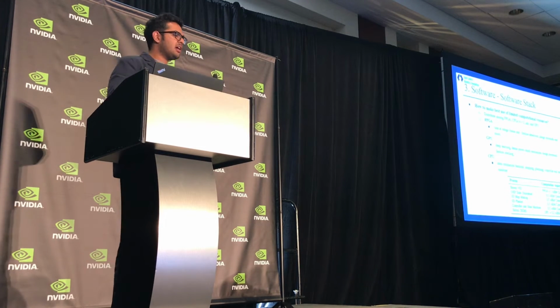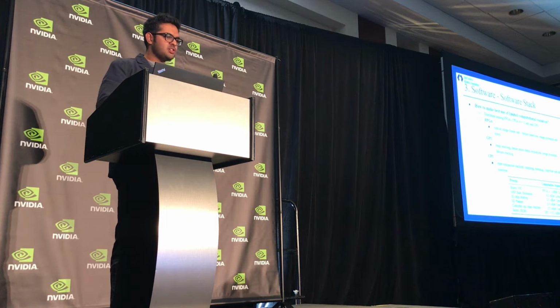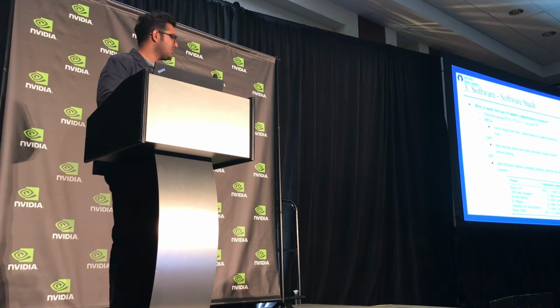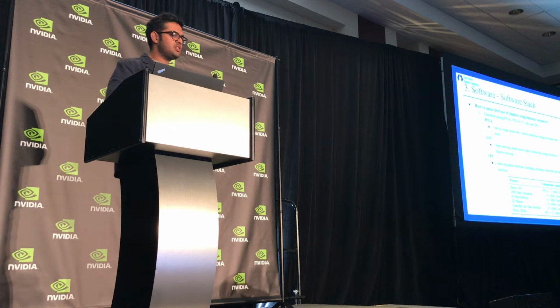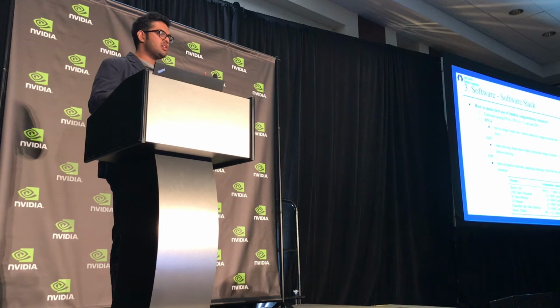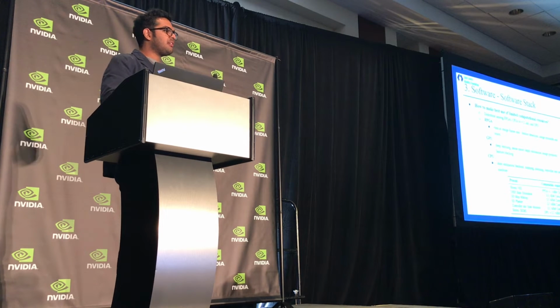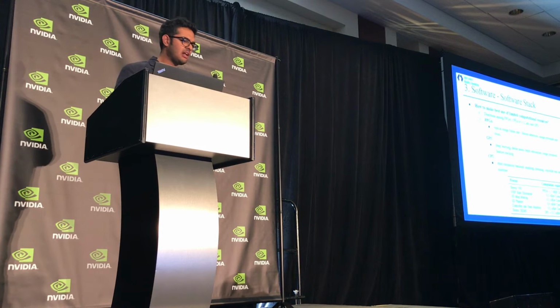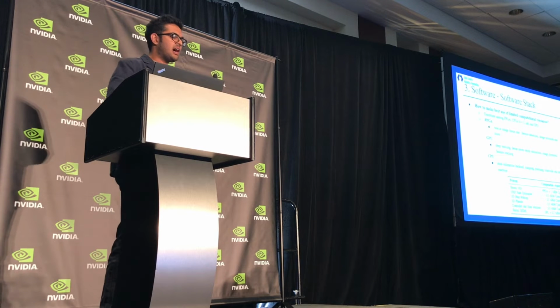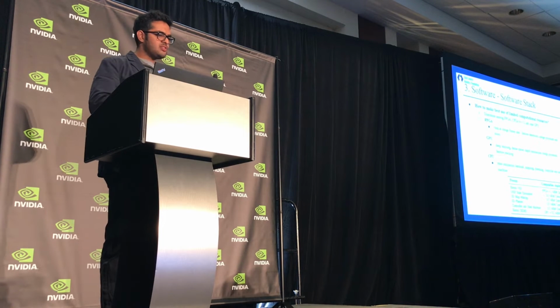Adding the FPGA can do stream rate computations, but programming an FPGA isn't as easy as writing something like CUDA, which is more developer friendly. So right now we do very simple tasks on the FPGA. For our state estimation, we do stereo feature matching, and we detect these features on the FPGA using FAST corners, and that's done at stream rate. On the GPU, we do deep learning, dense stereo depth estimation, calculating image pyramids for tracking, and the rest of our planner is usually on the CPUs.